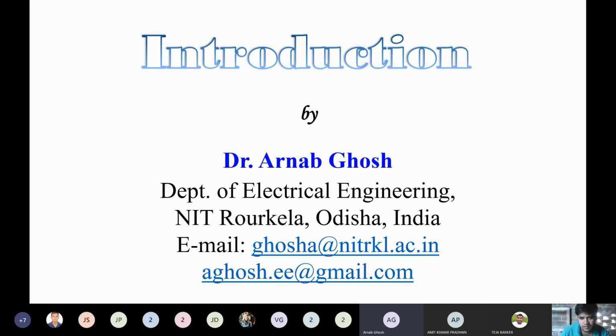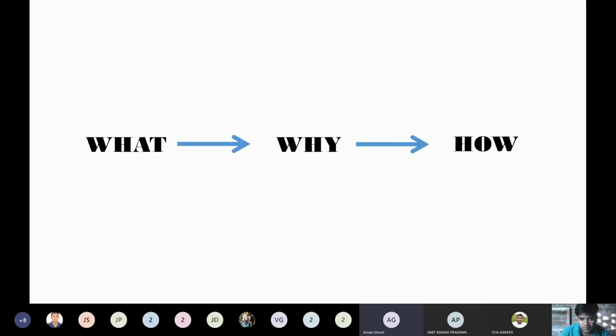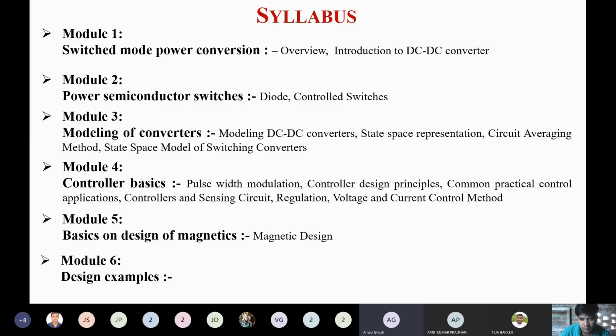And in case of the saturation region, what happens? In the saturation region, the current will be flowing continuously, but there is no voltage difference, because in a short circuit path the voltage is zero, but the current will be the full load current. So finally, what will be your power loss? The power loss will be V into I again, that will be zero. That's the basic motivation.